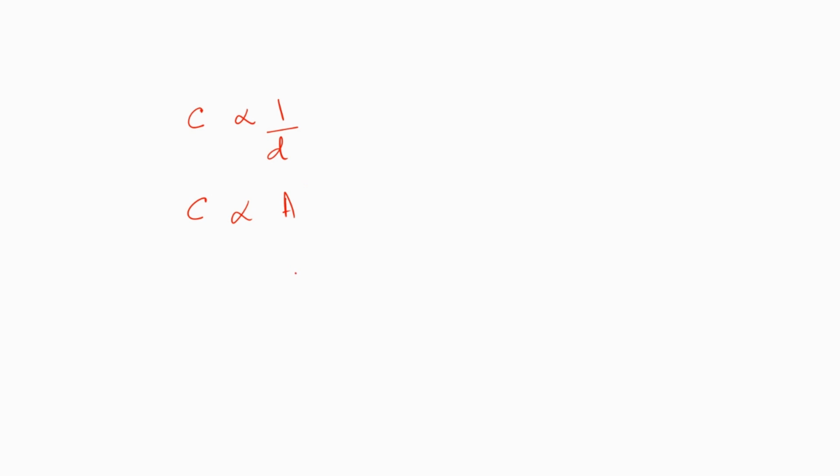Let me call that A. It is also going to depend directly upon a parameter called epsilon, which is nothing but the permittivity of the dielectric. So, we can put together the three terms and say that the capacitor has a value of C, capacitance, given by epsilon A by D.